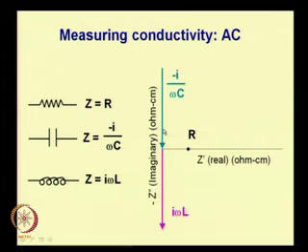What I just described I have shown you in a plot here. For a resistor, the value of resistance is R. What we normally plot is the imaginary impedance on the y axis, actually the negative of the imaginary impedance, that is just the convention, and the real impedance on the x axis. And what we see is for a resistor you get a single point. Please remember that this is data that is collected over a wide range of frequencies. At every frequency you can see what is V, what is I, and measure an impedance. For a resistor it makes no difference.